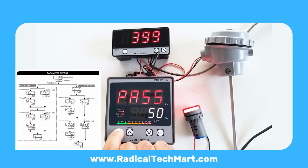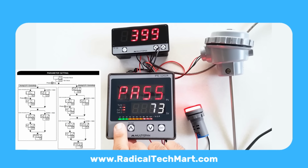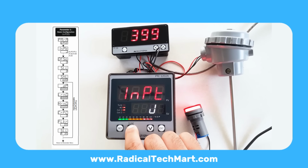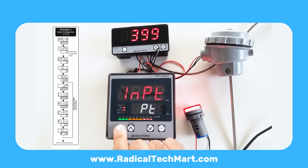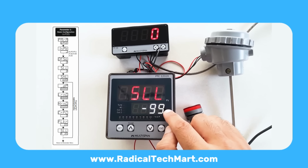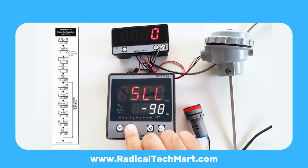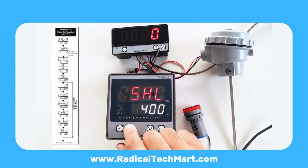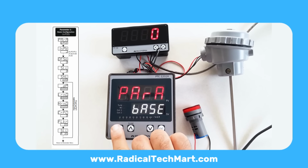To enter parameters, press and hold set until PASS appears. Password is 73. Press set to enter. Parameter: base. Input type, choose PT100, TC J K R E, or 4 to 20 mA, 0 to 10 volts using up-down. Offset, calibration trim, default 0. SLL, set lower limit, minimum allowed set point, example 10 degrees Celsius. SHL, set higher limit, maximum allowed set point, example 400 degrees Celsius.